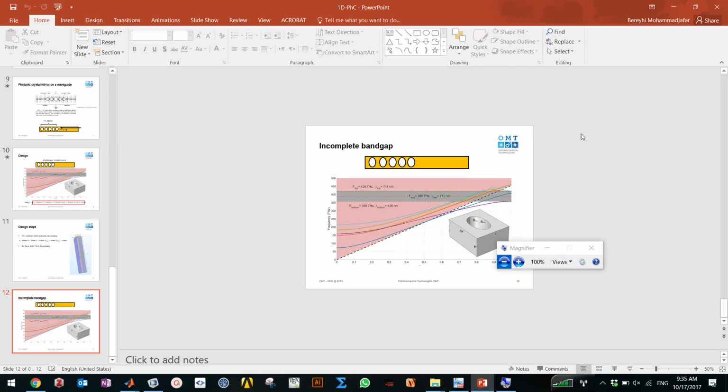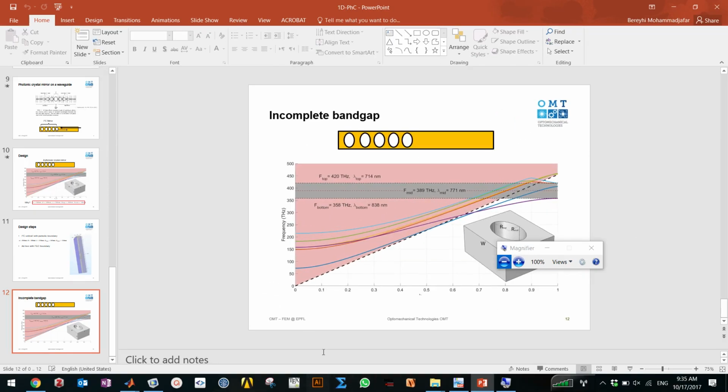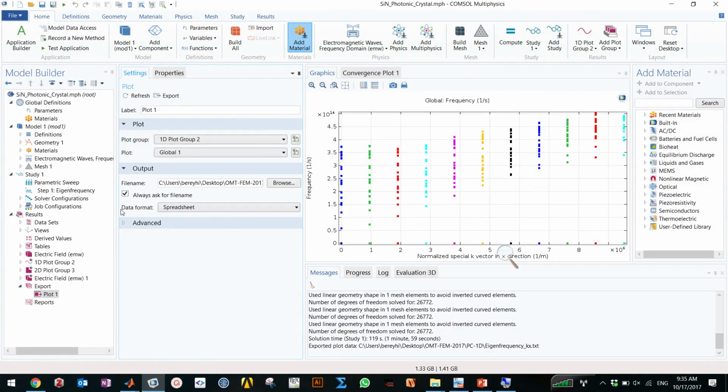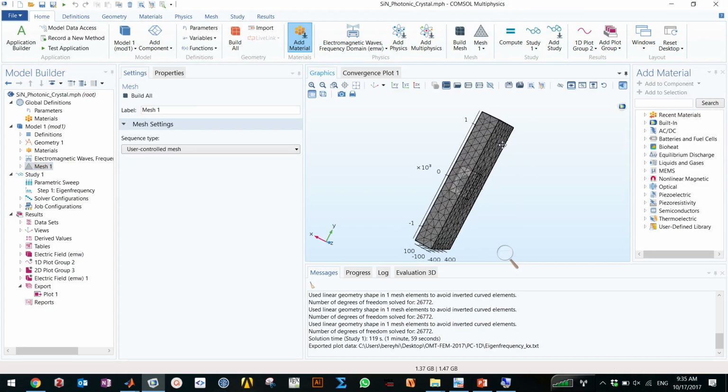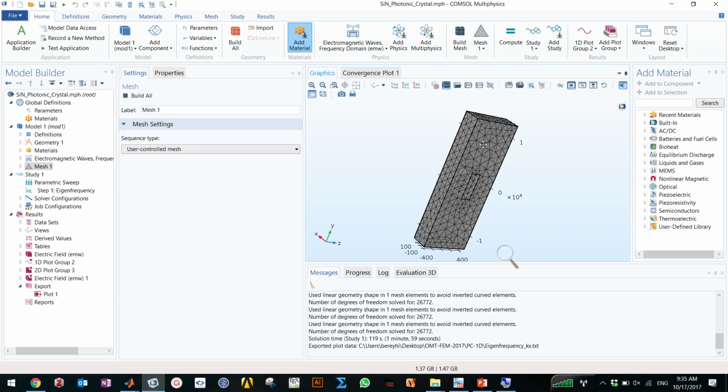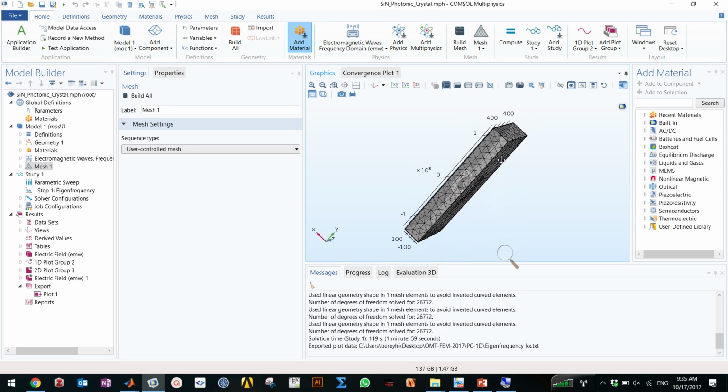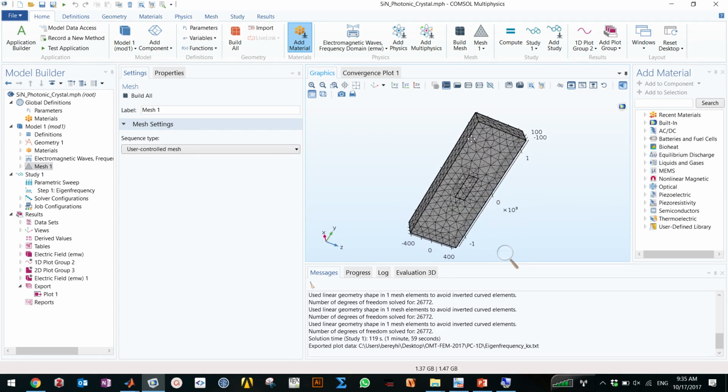I have a question on your meshing of the photonic crystal. Do you have to consider discretizing the mesh with a smaller or higher resolution than your waveguide that you're solving for? Why should I do that? Because in principle, if you discretize the mesh with a coarser resolution, then your mesh can't really see your wavelength, right?